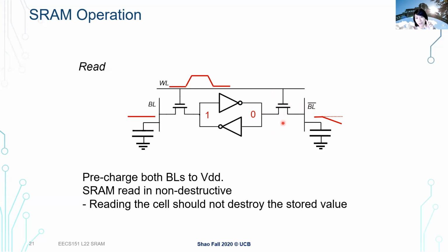So in this case, what's happening? Because I have 0 and 1, I have a voltage difference here. It's greater than threshold, so my transistor is on. So I start discharging my load capacitors here, to gradually pull my 1 in my bit line bar to be 0, because I have a 0 being stored internally. Right, so now I start this discharging operation.